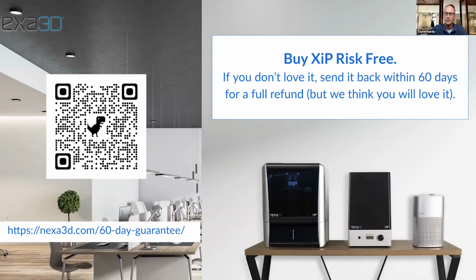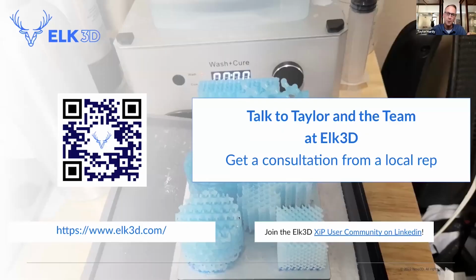Well, and just so everybody knows, on the other end, with things that you buy open source that are incredibly high viscosity, you have to be aware that you're using the correct profile. That's going to require a little bit of testing. Obviously you want to pick the right orientation, but you also have to make sure you've got the right supports, and you're not going to get any kind of warping issue when you go to print. So it's really somewhat easy. You just have to use a little bit of caution.